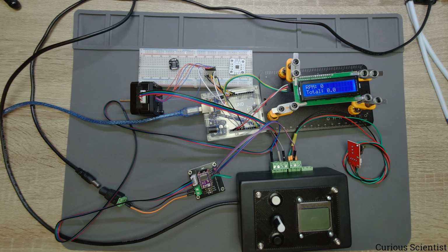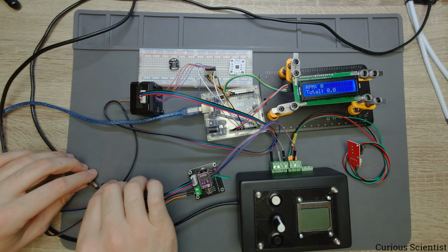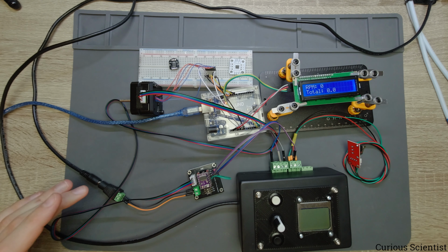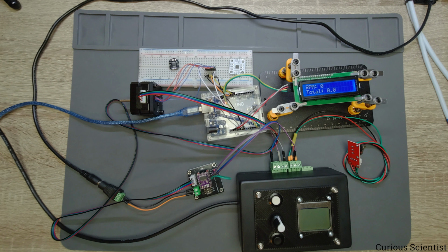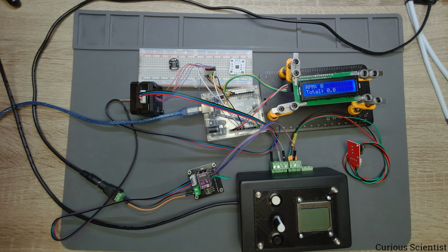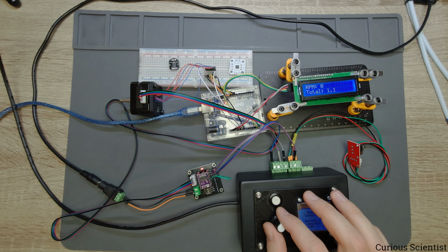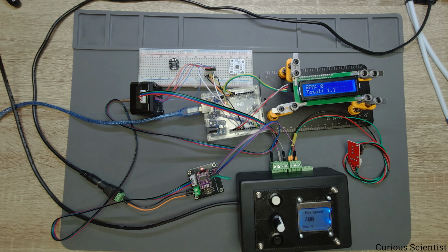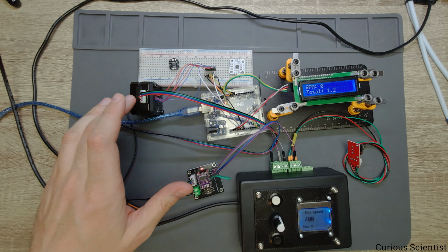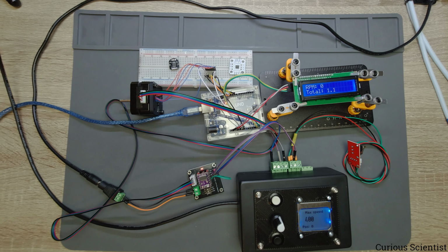And now I just connect the stepper motor part and see what is happening. So power is connected, and then I connect the USB cable. So now this is also on. So what I'm going to do now is I will run the stepper motor here with 400 steps per second speed.